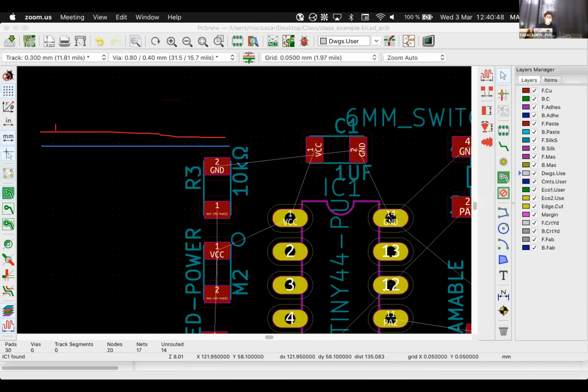And I put, for instance, a resistor here and another resistor here, etc., with the footprints like this one. So this is that. And then the microcontroller, I put it on the other side, and I put it here. The hole, in this case, can go here. And the pad goes here. And the leg of the microcontroller, in this case, comes here. And I have all the solder on the same side, and I close it in here.